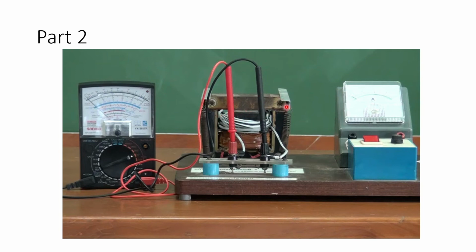From there, you're going to be reading how the transformer works by wrapping this wire around here, and then rewrapping it again on the side. By wrapping on the side, you would notice that the magnetic flux is going to be half, because the magnetic flux comes out and is split into two halves. So if you wrap at the center, you get the full magnetic flux, but if you wrap it on the side, you get half the magnetic flux. By getting half the magnetic flux, you should get half the reading as well. So be sure to compare that with the calculation of the EMF equation based on the number of rounds.